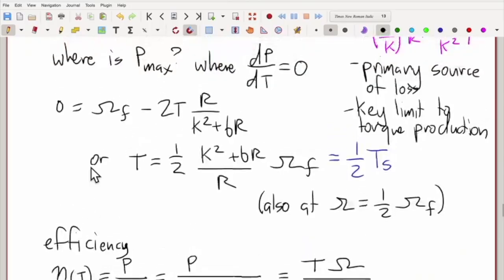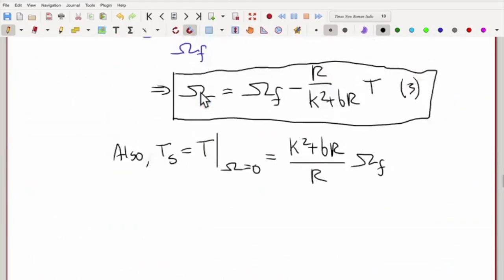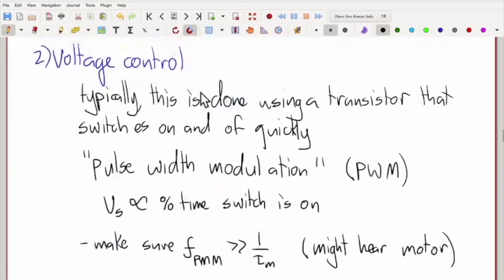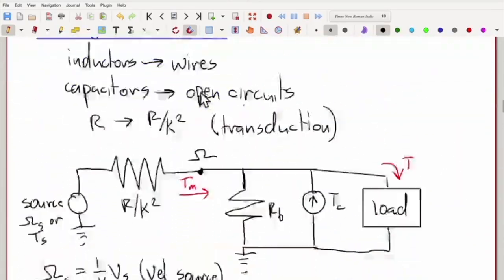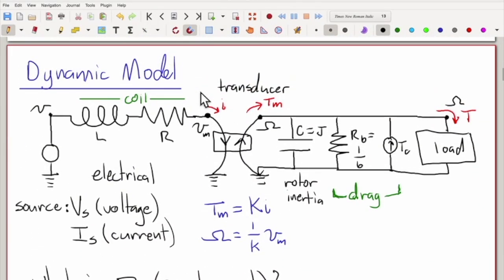And you have now the tools, through system identification, for example, to derive a plant model. What you would do is take this full model at the beginning of the motor, and add in a model of your load, which is intimately connected to this.